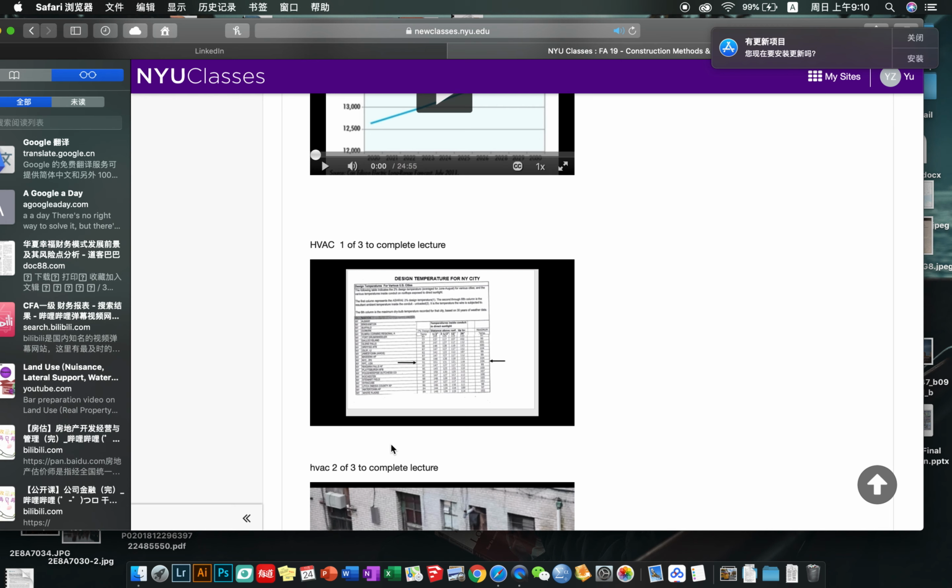But again, in this particular chart, you can also see in that middle section how the temperature within a conduit that's exposed to some kind of direct sunlight also heats up well beyond the stated air temperature in the area. So it's just another example of how the sun and radiation and heat build up in areas just like within a building. Even though the stated temperature is 91, it can feel much hotter inside, and you have to account for that in developing your HVAC system.